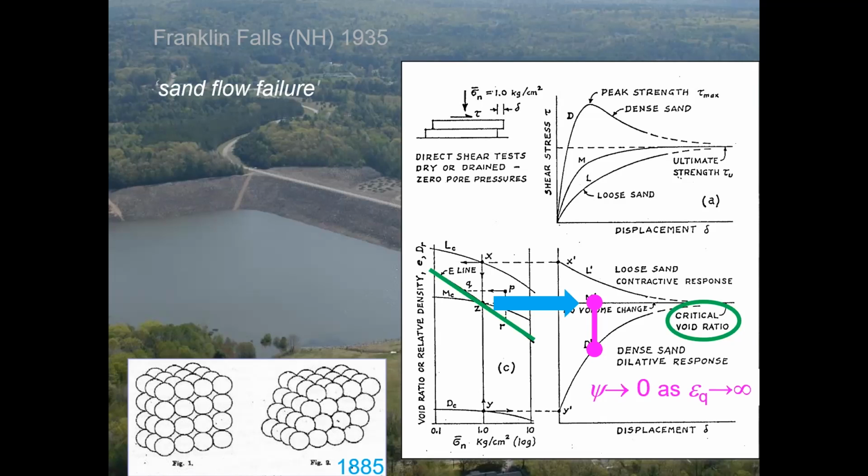And we treat that as a second axiom, that the state parameter goes to 0 as the distortion goes to infinity. And the nice thing about that is we can then do some mathematics around it, because we've taken a sketch from a geologist, and we've now said, well, actually, we can characterize that properly and formally. Once we've done that formally, we can then turn mechanics loose and derive a few things. And what we get out of this is that the stress strain behavior is the result of our derivation. It's not the start.